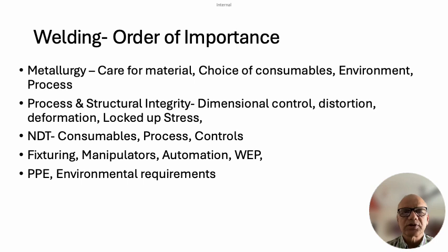You cannot do extensive fixturing when you have limited accessibility or limited movement, and then you have to do quite a large number of start and end points. Like titanium, if you have a large number of start and end points, it is not really good. The material is not as accommodating as carbon steel, where you can have as many start and end points, because of the flowability, the surface tension, the wettability of this material. Carbon steel, and to a certain extent stainless steel, is good.